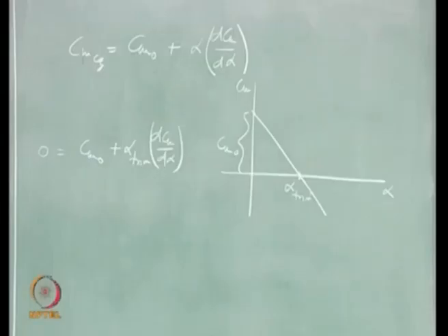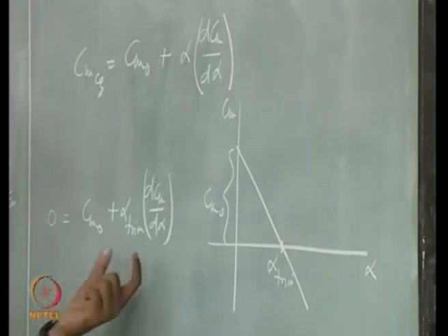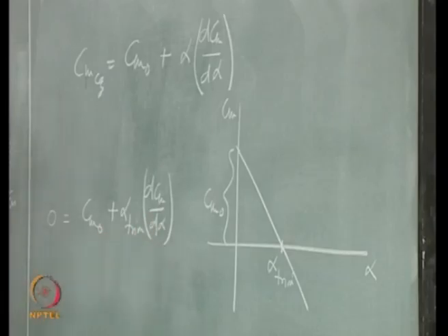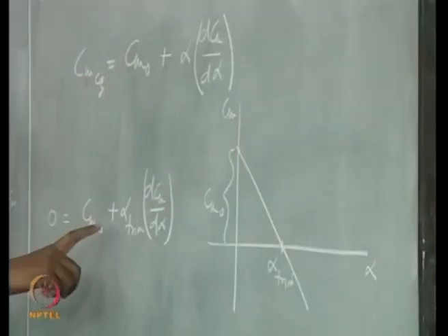Now question is, how do you do that? In how many ways you can get that? One is, of course, we started with, right. In the last class we said that we are going to use a flap at the trailing edge of the horizontal tail, which is called elevator, but let us say now we will go into that little later. Change the camber of the wing airfoil itself, right. Wing camber, if you change, this Cm naught is going to change, right. So you can change the alpha trim, right.